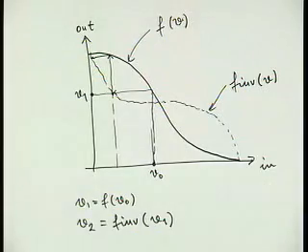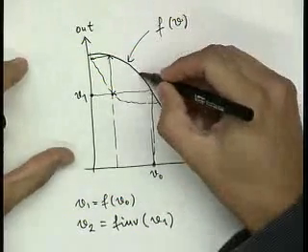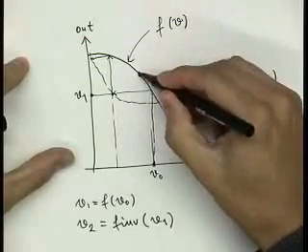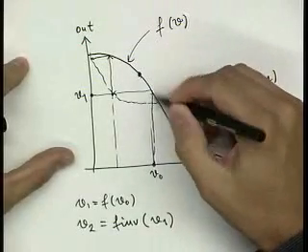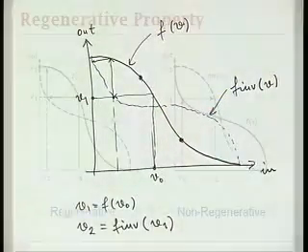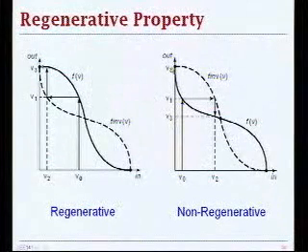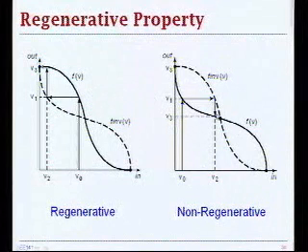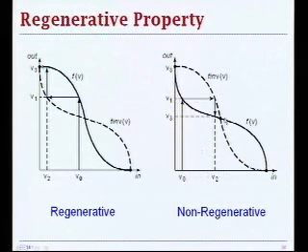So what provides this regenerative property is this gain region here, where you have a gain greater than 1 in absolute value in this transition period. So let's go back to the slides. If you assume a transfer characteristic with a gain in this region less than 1, then you would eventually settle in this undefined region where you have neither logic 0 nor logic 1, and that's basically how you end up there. So it's very important for gates to have gain to be able to sustain noise.